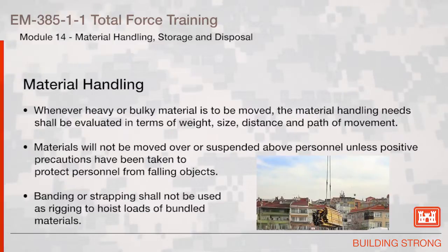Whenever heavy or bulky material is to be moved, the material handling needs shall be evaluated in terms of weight, size, distance, and path of movement. Materials will not be moved over or suspended above personnel unless positive precautions have been taken to protect personnel from falling objects. Banding or strapping shall not be used as rigging to hoist loads of bundled materials.